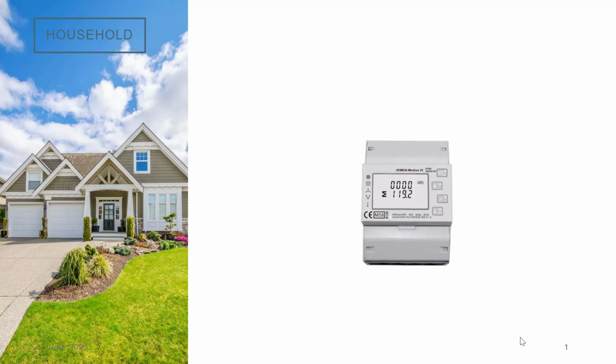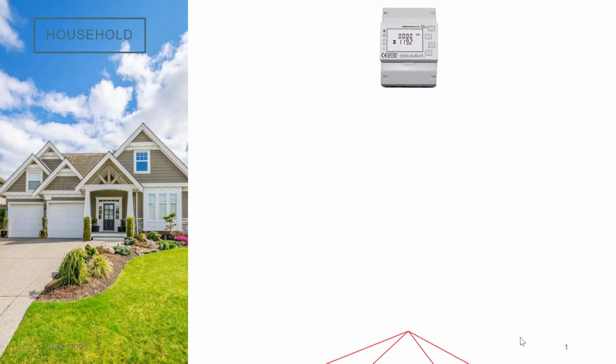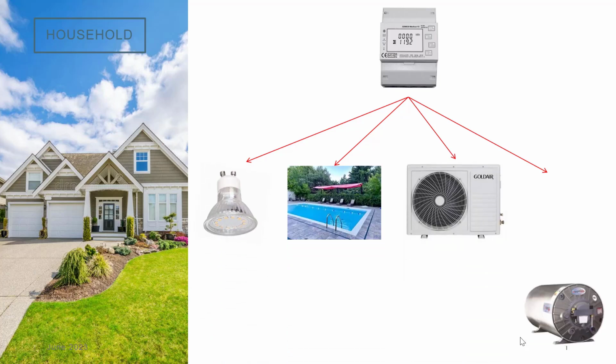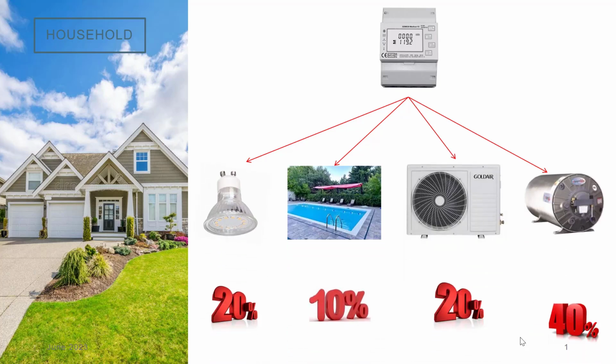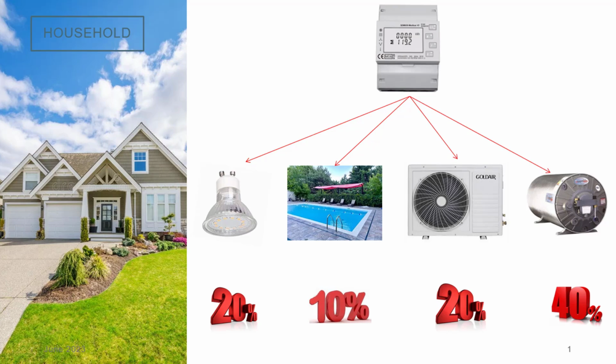You put a smart meter at the point of supply by Eskom and monitor hourly and daily usage. Then you identify and target high consumption points, e.g. lighting, swimming pool, geyser, air conditioning, and you make changes. You put a geyser timer, you put LED lights, you put a gas stove, you put a pool pump timer. You then monitor how the daily usage changes in the smart meter.